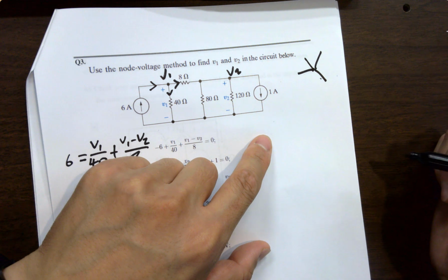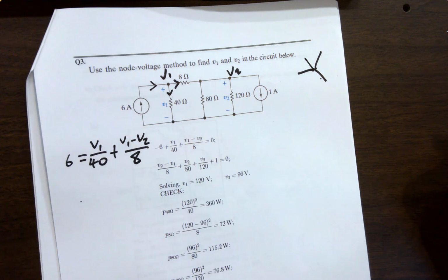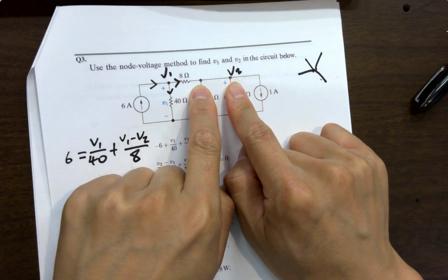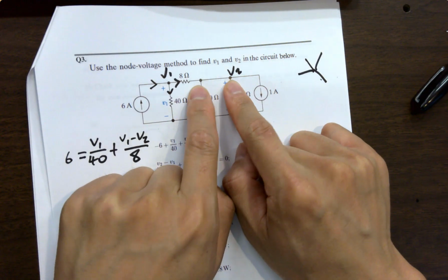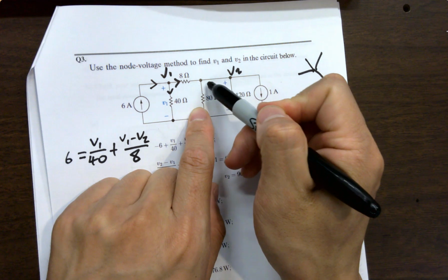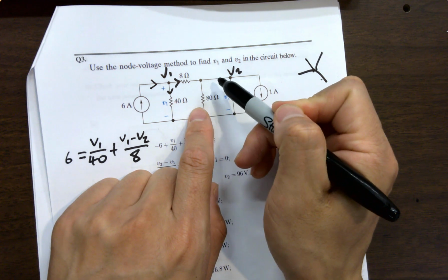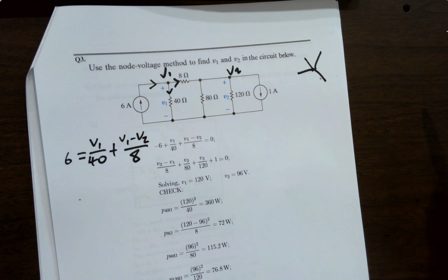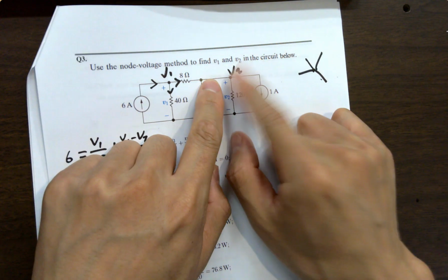Okay? So let's just list the one KCL. Can we do that? Why don't we want to list the 2 KCLs? Like you have one node, 2 nodes, so you have to assume a current here as well. It eventually gets cancelled, right? Okay? Let's just melt it. It becomes one node.